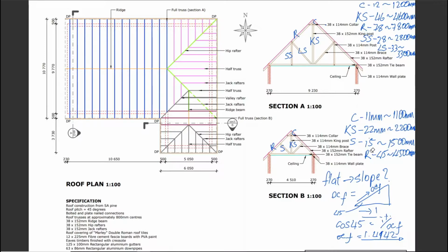That is important because it is going to help us convert any flat value to a simple sloped value. I say simple because we're only talking about values that run perpendicular to the face of the roof. Here's the face of the roof. Any value that runs perpendicular to this face gets this value here, our X factor. So we've got our X factor to apply to any of those slopes.